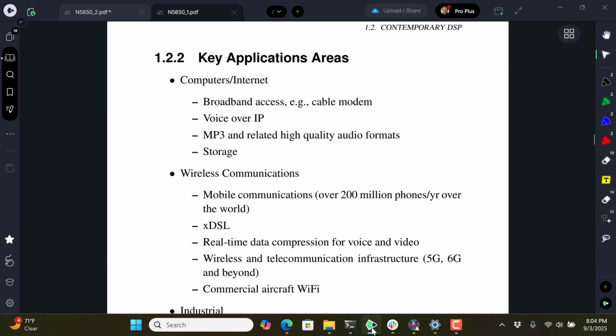It uses what's called pulse amplitude modulation, PAM, which has 4 levels as opposed to the older 2-level, and then because this is on a backplane, there was some transmission line modeling for getting the data in and off the disk. So that involved more than just DSP, but it also involved some microwave circuit design.